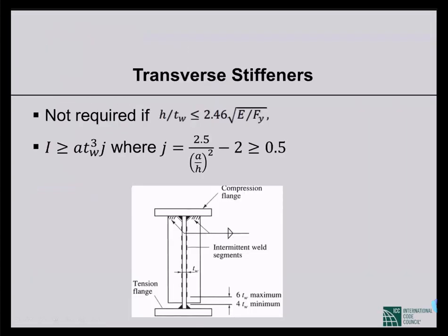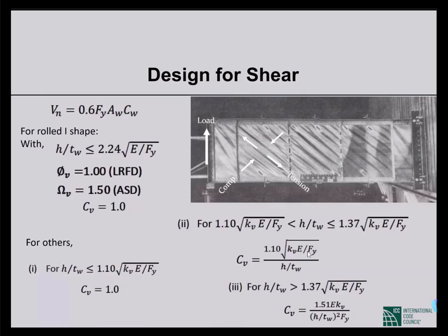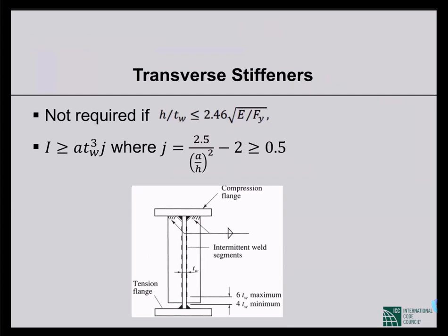Now, as you see, suppose we didn't have the stiffeners, then it would buckle much earlier. And if we have more stiffeners, that is, if we divide the panels into very short spans, then the buckling will be induced later. That is, it can take much more load before it buckles. So that is the purpose of transverse stiffeners along the web.